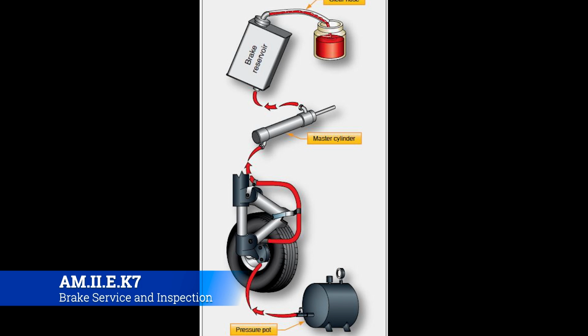In either case, you should always MOC them while they're on the ground. So do a maintenance operational check, step on the brakes, make sure they're hard, and then whenever you actually go to return the aircraft back to the customer, you're going to go through all of the checks at the end of the annual or whatever service you're doing. You should always crank it up, taxi it forward, step on the brakes, make sure the brakes work fully. Because what you don't want to do is return the aircraft back to the customer with faulty brakes, and then it would be an unprofessional look on you, but also could be very unsafe if it's not caught in time.